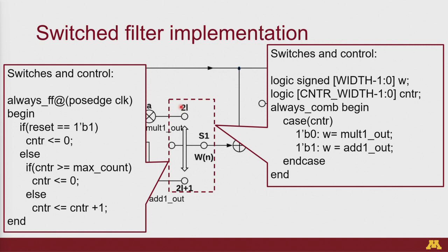From a Verilog point of view, that just means implementing a counter which counts up to 5. When the counter value is 0, you do 5L plus 0, when it is 1, 5L plus 1, if it is 2, you do 5L plus 2 and so on. Does that make sense? I hope this part is clear, because you will keep seeing this throughout this course.